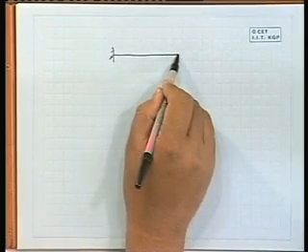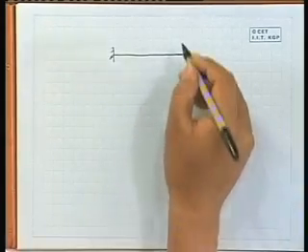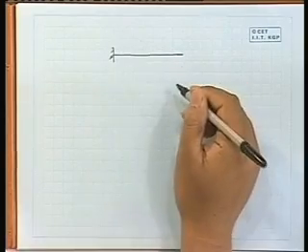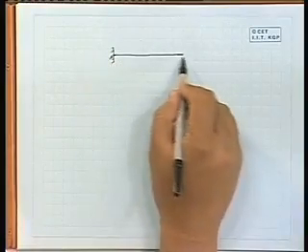Now, if I take some example, cantilever is a very good example in that case, because say this is a cantilever problem and this problem you have solved by your differential equation technique. Some of the information is already there. So, we can compare our result at this level using moment area theorem.